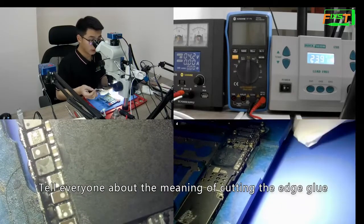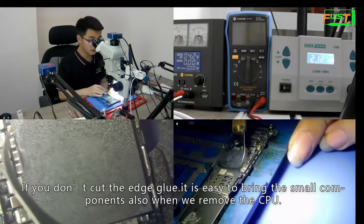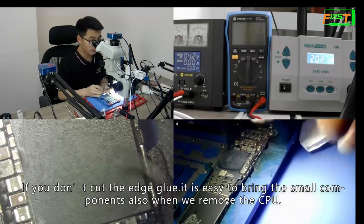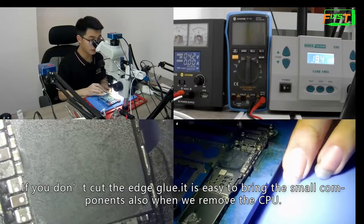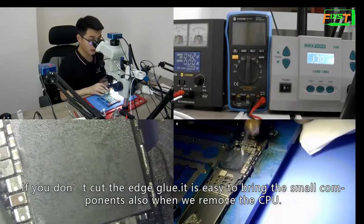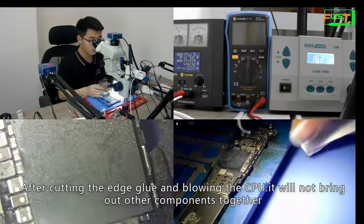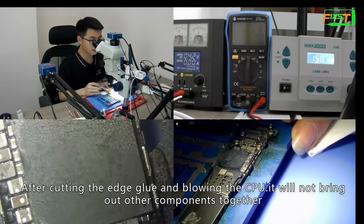I will tell everyone about the function of cutting the edge glue. If you don't cut the edge glue, it is easy to bring the small components along when we remove the CPU. After cutting the edge glue and heating the CPU, it will not bring out other components together.